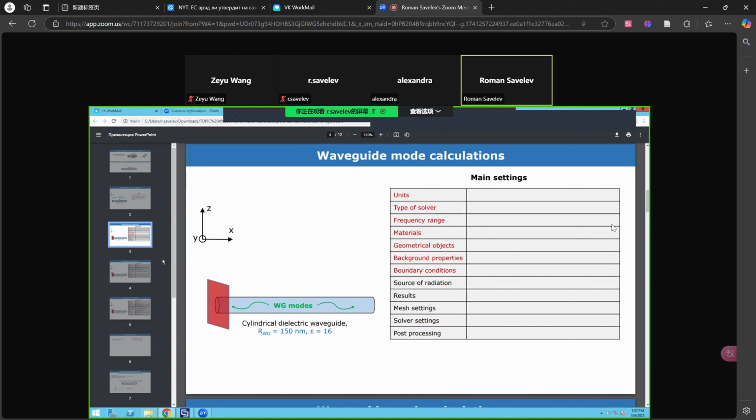It doesn't matter what happens outside of the port. So the easiest way is just to set it as 0 by default. Even if we wanted to excite this waveguide, we could still set this background distance as 0, because if we choose the size of the waveguide port properly, then everything is fine. So this is the distance that we need.